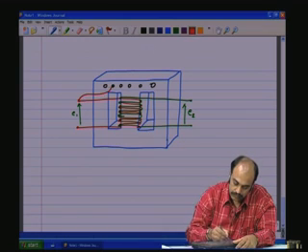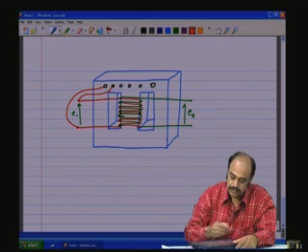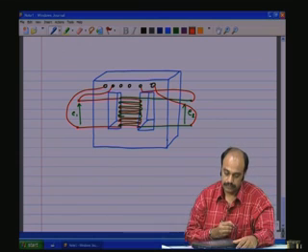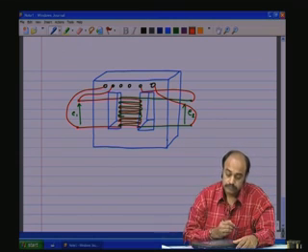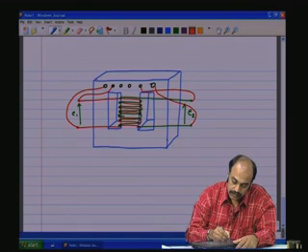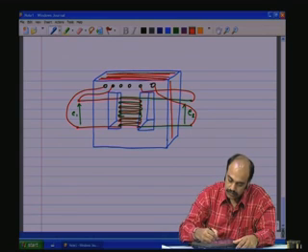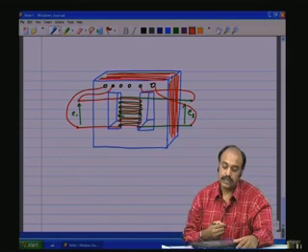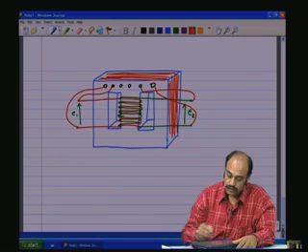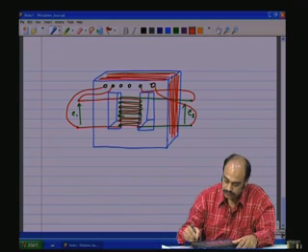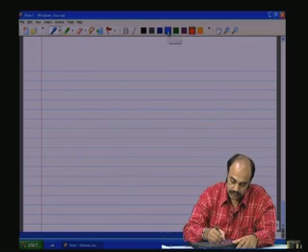So, you could have these points which are soldered onto this, and the secondaries which are soldered onto this. And these are the laminations which you will see, the lines here, which are the thin laminations of the grain oriented silicon steel. Okay.